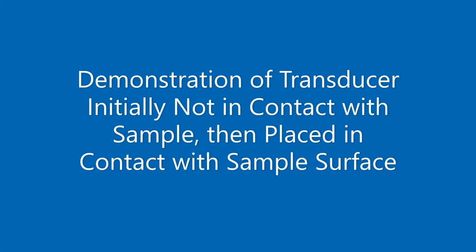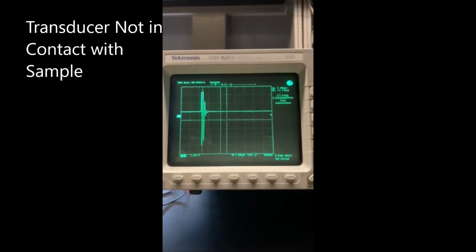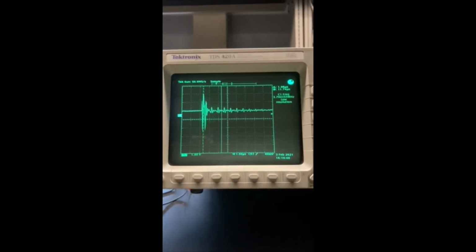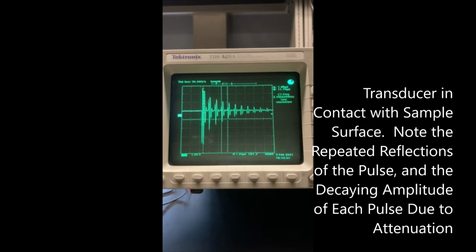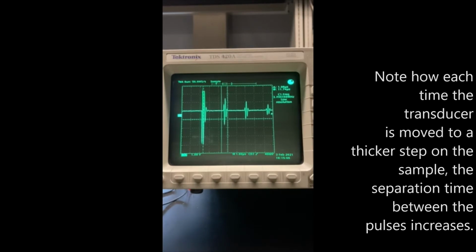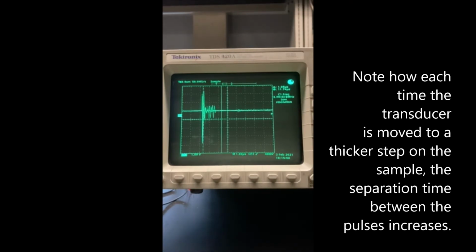You'll notice here how the gap between the pulses keeps getting longer as we move from one step to the next. As the steps get thicker, the time delay between the pulses increases. So here you can see a very large time gap between them. And as we go to thicker steps of the samples, you can see even larger time gaps between the transmitted pulse and the receiver pulse, and between the pulses as they bounce back and forth through the sample.